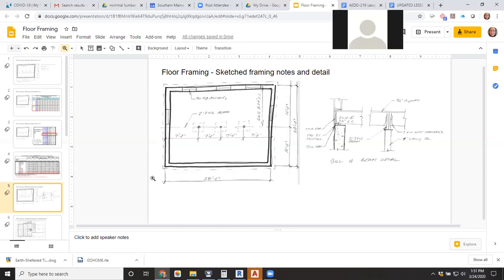You'd probably make it for the longer span and then equalize that for the other, so it would be the same across the board, or would you make them different sizes? The floor joist, yes, but do you see that the beam size would not change? Because the beam size is not being affected because the width of the building didn't change, the number of stories didn't change, right? And our lally column spacing did not change.